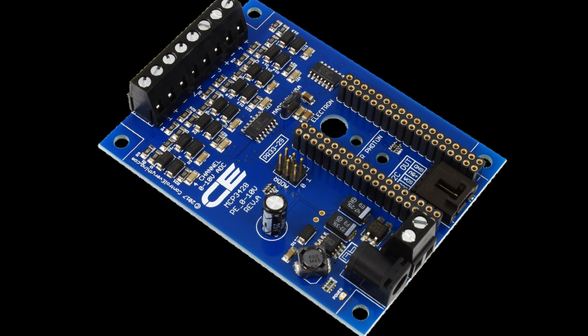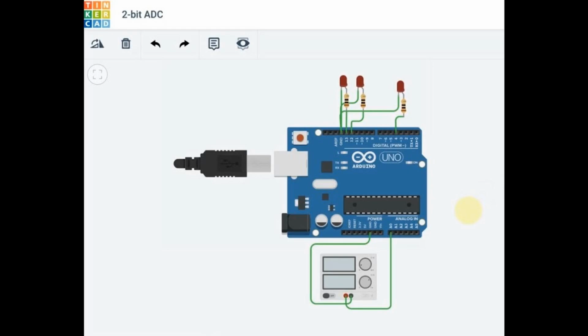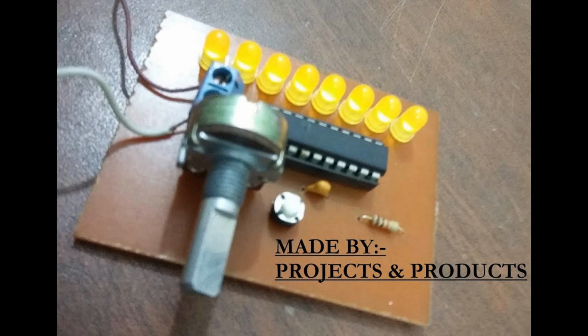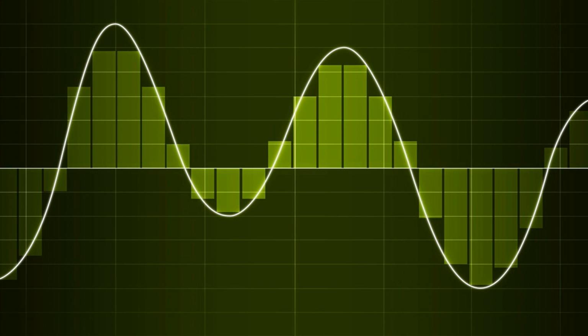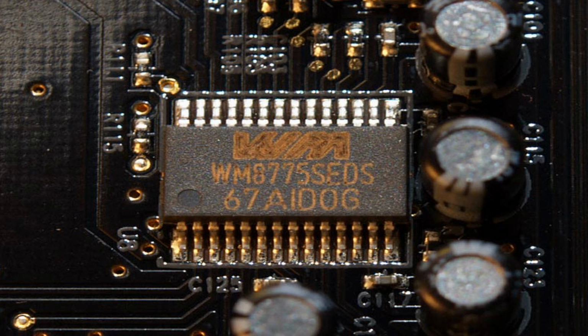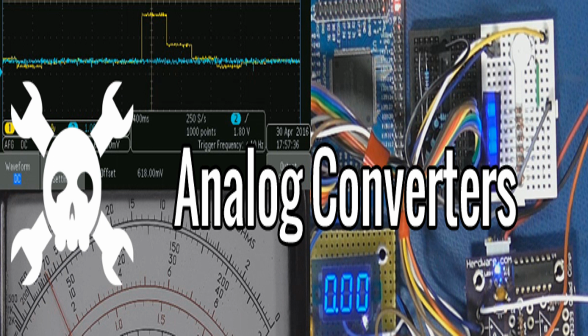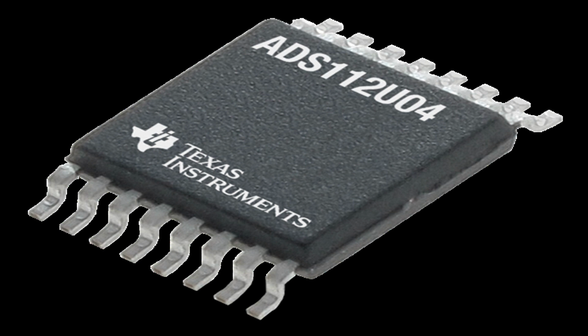The ADC converts the analog electrical signal into digital data by a process called sampling and quantization. Sampling involves taking measurements of the analog signal at regular intervals, and quantization involves assigning a numerical value to each sample based on its amplitude. The rate at which the analog signal is sampled by the ADC is referred to as the sampling frequency, and is measured in Hz. The higher the sampling frequency, the more accurately the ADC can capture the original analog signal.